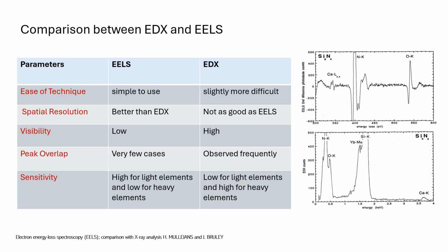Now both EDX and EELS are widely used for the material science, and this is just a comparison between the two techniques. It's not to conclude which technique is better, but just to compare between them. For the ease of technique, if we consider only the ease of technique, the EELS is simple to use, where EDX is slightly more difficult than EELS. The spatial resolution of EELS is better than EDX.